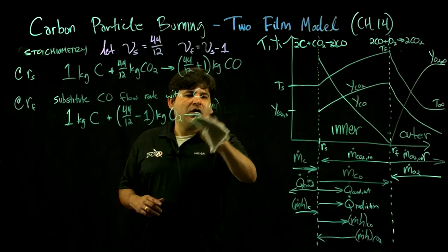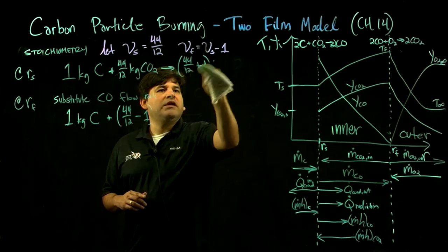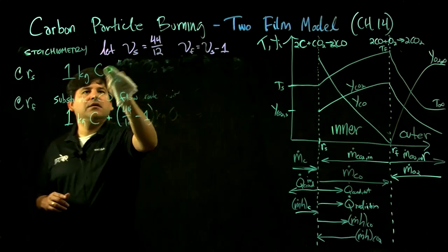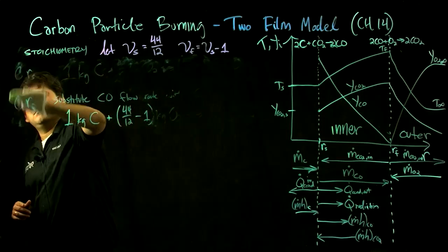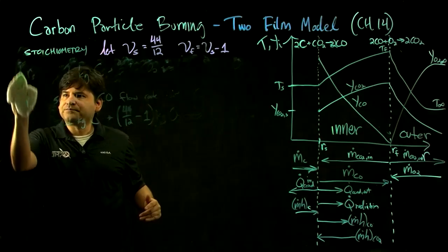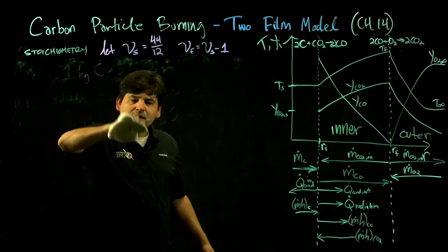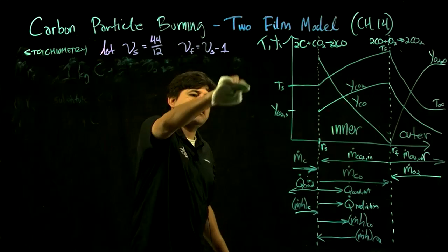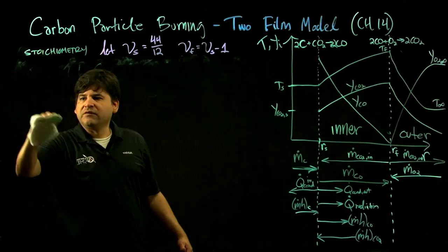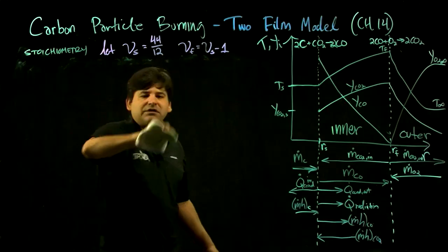Okay, so let's move on to the species. We're going to have CO2 that we need to track. That's being formed at the flame, and then it is used to oxidize the carbon. Let's write the species equation, which without any bulk convection has just transport by diffusion. That's one form of the Stefan problem that we've worked on before, in radial coordinates. So it's similar to the droplet evaporation and droplet combustion models that we've worked with.